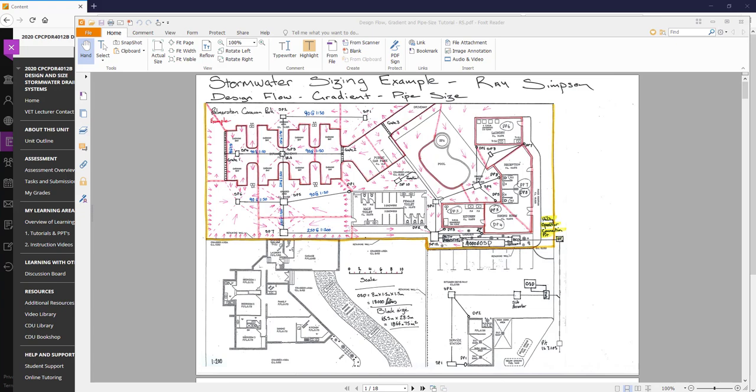We have a silt arrestor as well to capture all the silt before it goes into the drains, where we can do our maintenance. And then a series of pits starting up here with SP1, Stormwater Pit 1, SP2, Stormwater Pit 2, and so on. What I've also done is I've broken the whole property into zones, as you can see, and worked out approximately how many square metres goes into each zone. For instance, SP1 is capturing approximately 20 square metres.